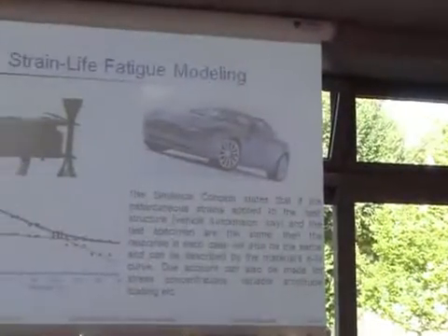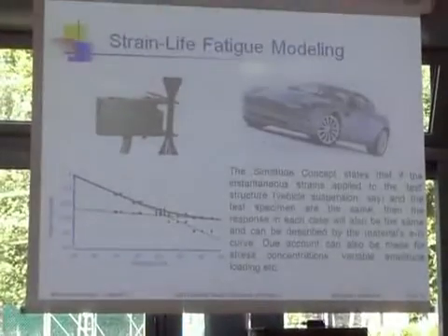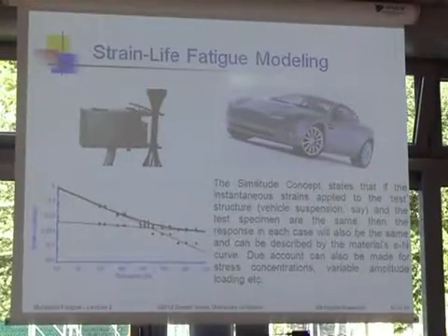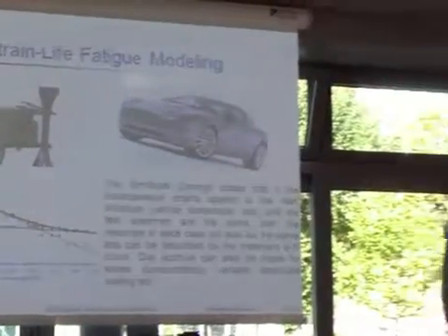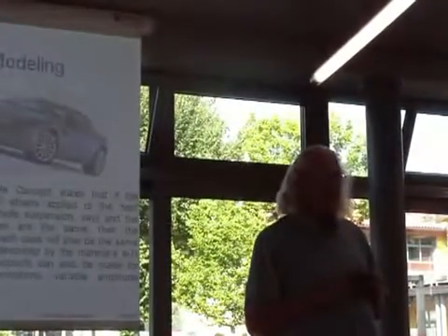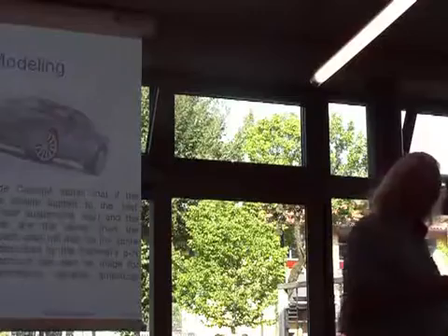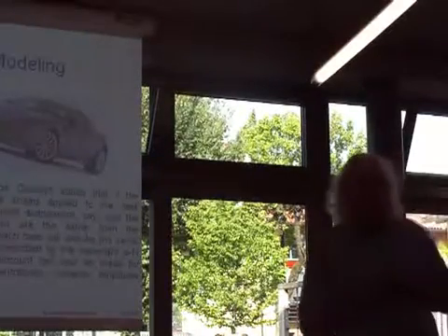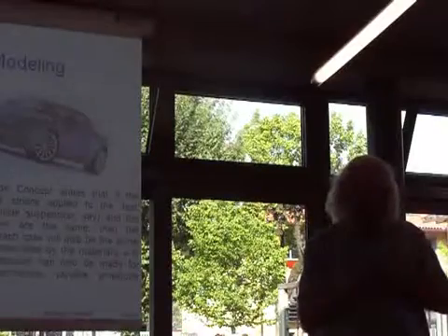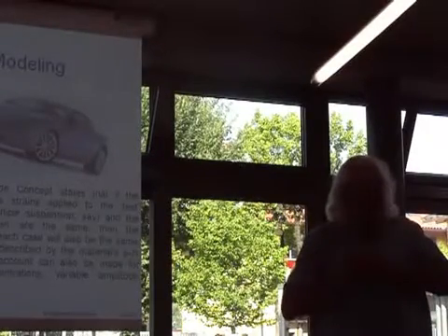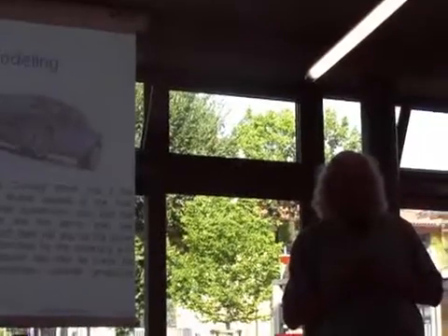If I want to find cracks here, the best thing for me to do is to go into the parking lot and take a look at the engine. And I believe I will find cracks in almost every engine. The place I will find them is actually not the intake manifold, but at the valves in the exhaust ports. Every time you start and stop your car, it heats up. There's this very small bridge in there that undergoes a tremendous thermal cycle because it's restrained by all the cool material around it, and they crack almost right away.